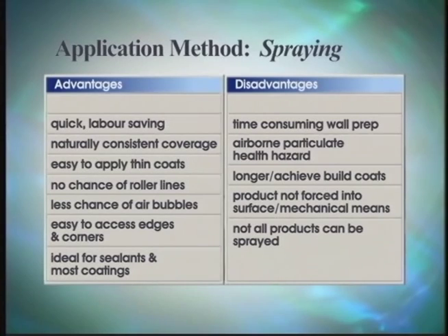Disadvantages: Time-consuming wall preparation must be done. Airborne particulate health hazard. Takes longer to achieve build coats. Product is not forced into the surface by mechanical means. Not all products can be sprayed.